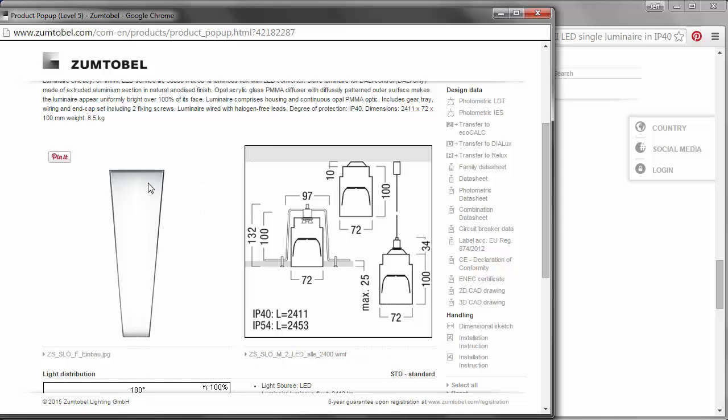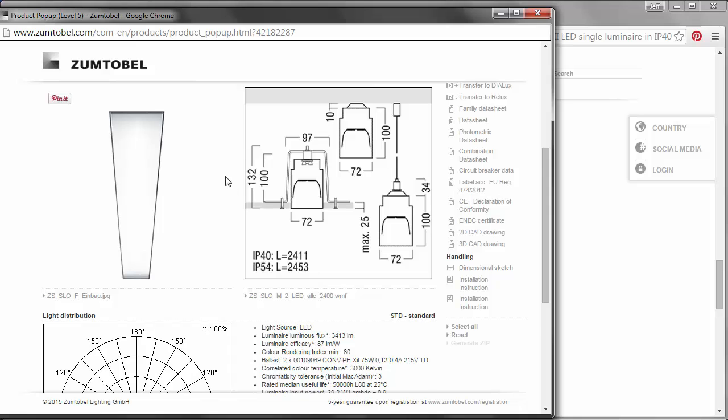It should be noted that the IES file that we bring in brings some geometry into the Rhino scene, but it's really just a flat plane. It's kind of like a representation of the bottom diffuser of this light fixture. It doesn't have any geometric information about the housing. And so we have to reference this information and make some assumptions about the housing to inform the way that we locate the light fixture in the scene. And I'll go into that in a little bit more detail in the subsequent steps.